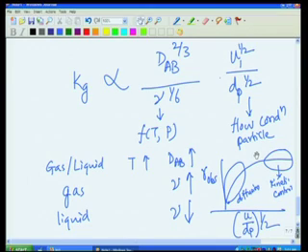So, knowing Kg for mass transfer, and the heat transfer coefficient hF, we can make the same arguments for temperature as what we did for mass. The only difference is, instead of rate of reaction, we will now equate the rate of heat generation, that is energy generation because of chemical reaction, to the rate of energy transport.